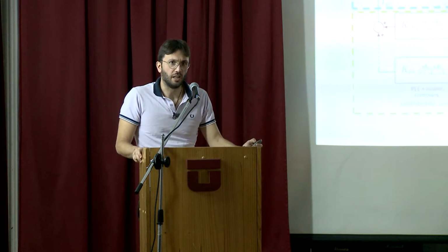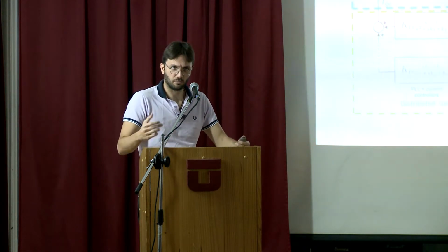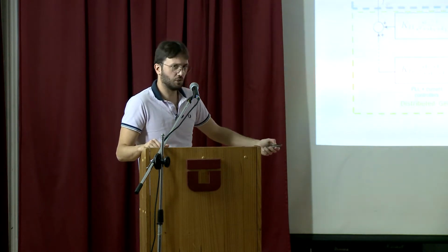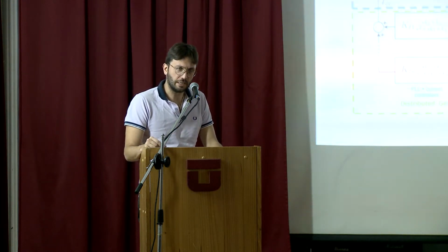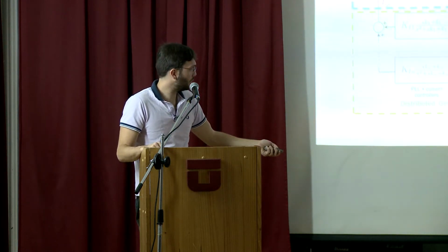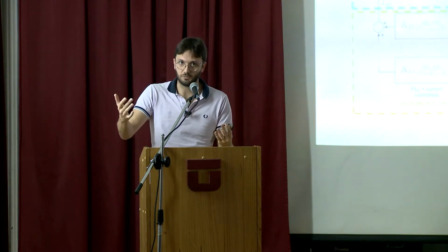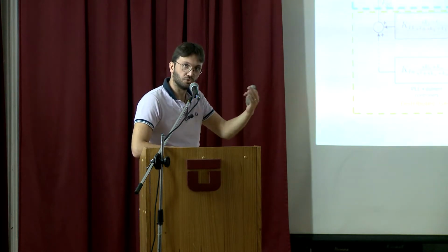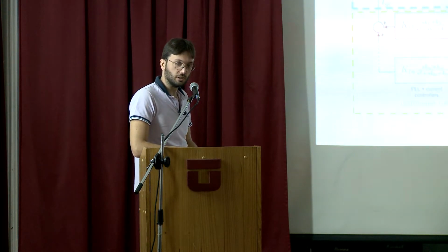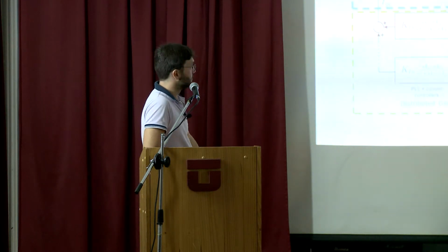These values are kind of small, probably, because they are considered with the per unit PLL. If we consider the one with the voltage, this would be like 300 Hertz. That is maybe more familiar for people who design the PLL, considering also the amplitude of the grid voltage. But this is just modeling.